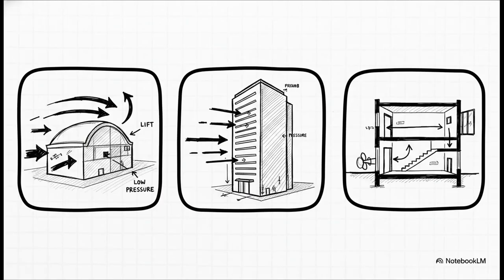Okay, so how does this translate to your ARE exams, especially for PPD and PDD? Well, this principle is the entire reason we have to calculate wind loads. When wind zips over a curved roof, it accelerates, creates lower pressure, and that's lift. Your structure has to be designed to resist being pulled upwards. Understanding this is key for structural questions, and it's also the scientific basis for a lot of the passive, wind-driven ventilation strategies you'll see on the PPD exam.